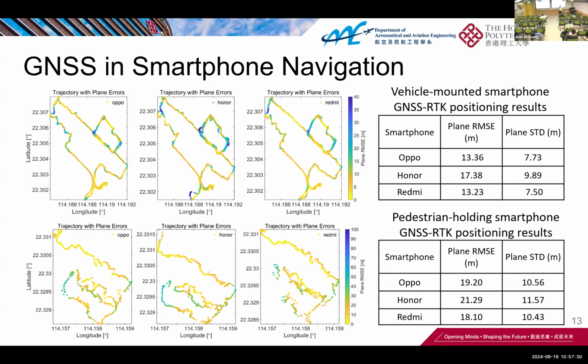For example, when driving a car, you have some constraints. If I drive a car, the vertical speed should be 0, because I cannot jump. Also, the lateral speed with respect to the lane line should be 0. Those are very strong constraints that can be applied to the positioning estimation. And usually a car keeps a constant velocity over a short period. Based on this model, we can easily improve the accuracy. That's why, when going straight, it can at least reflect that it's a line.